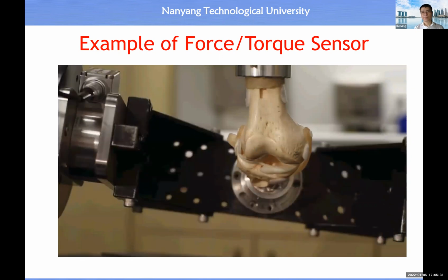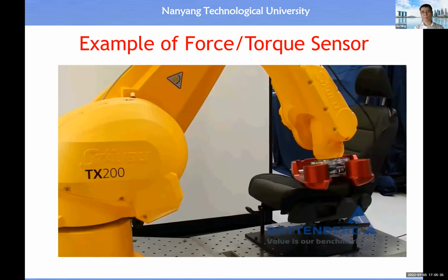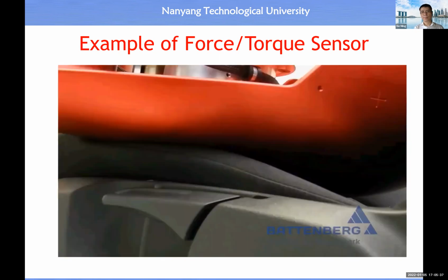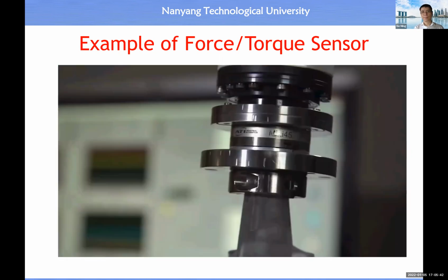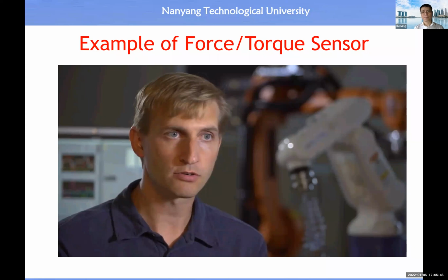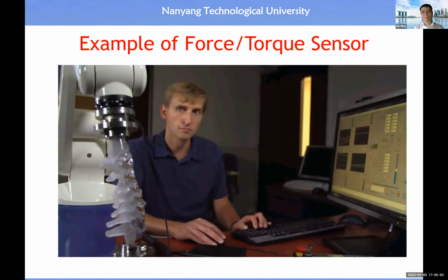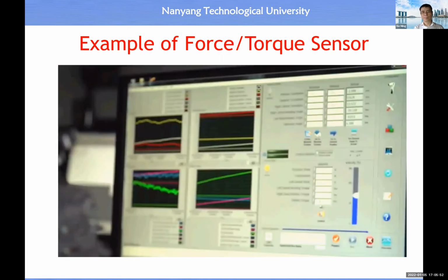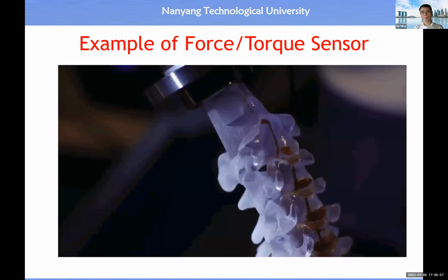Some of the more common applications for force torque sensors are product testing, life cycle testing, control of robots for surgery. The robotics technology with the full 6 degree of freedom control gives you a lot of freedom that you never had before, because you need to be able to measure 3 forces, 3 torques to get the full loading state of any joint. And that's true for any joint. Once you establish that, you've established the full loading state of any specimen of any joint you want to do.